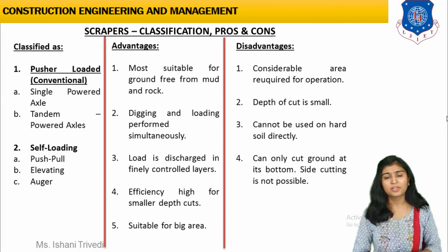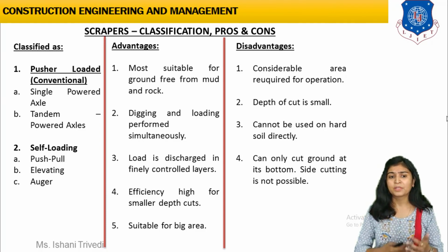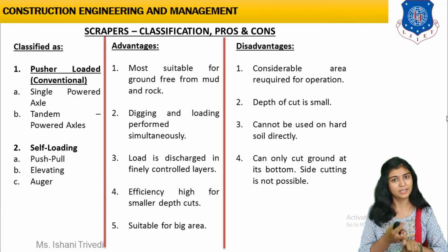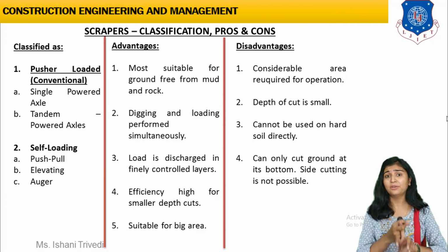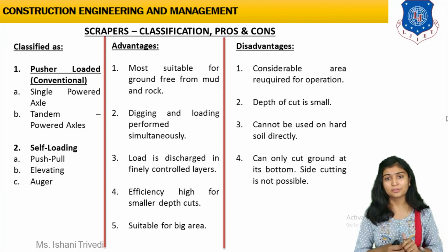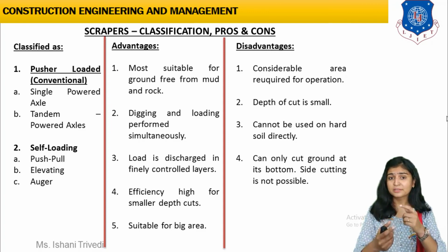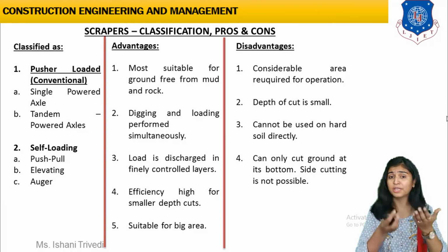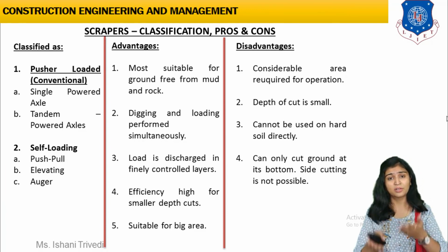Next, if we talk about advantages and disadvantages, if I want to write it on my own, then I can say that it is most suitable for large areas. You can work in larger areas, correct? That point will be there. Then you have to deal with soil which is free of rocks and mud, right? You saw the working already right now. So this contradicts the ripping process. Once you have ripped the soil, you will have to first remove the heavy boulders and rocks and then work with the help of a scraper.